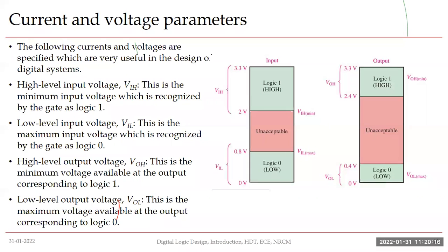They will also decide the logic levels we can use without the effect of noise. They will also help us decide the transition levels, so that in the presence of noise, we can still make the correct decision whether we have logic 1 or logic 0 at the input.